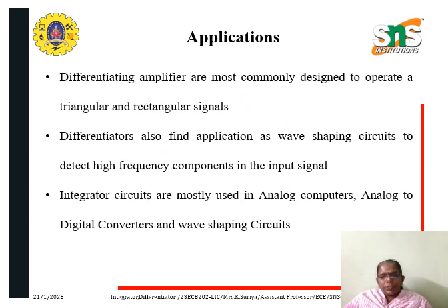So the applications of these are: differentiating amplifiers are most commonly designed to operate on triangular and rectangular signals. Differentiators also find applications as wave shaping circuits to detect high frequency components in the input signal. Integrator circuits are mostly used in analog computers, analog to digital converters, and wave shaping circuits.